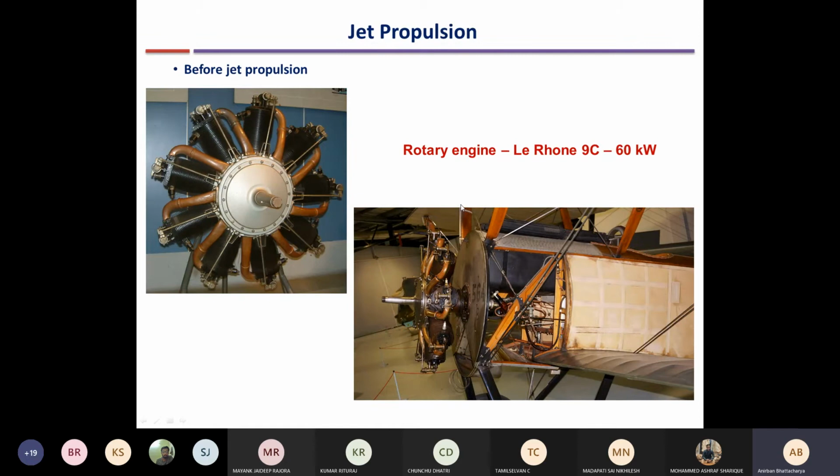Okay. So the first type of prime movers, or the first type of engines that were developed, as you might know, were the steam engines. They were developed towards the end of the 18th century and became quite popular in the 19th century. These were engines where the working fluid was steam, and they were reciprocating steam engines, not steam turbines. They were somewhat similar in nature to your petrol or diesel engine, but instead of internal combustion, the combustion was external. So these were external combustion steam engines, EC engines, not IC engines.